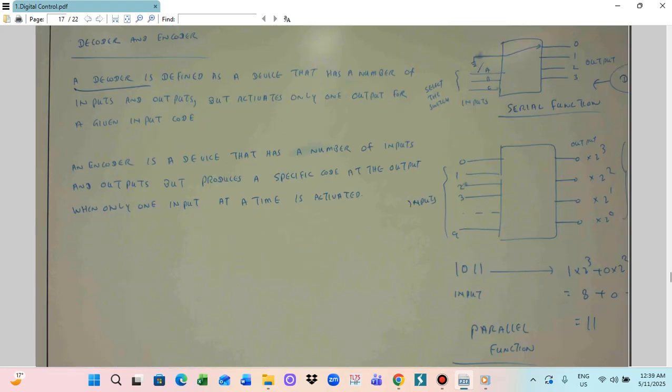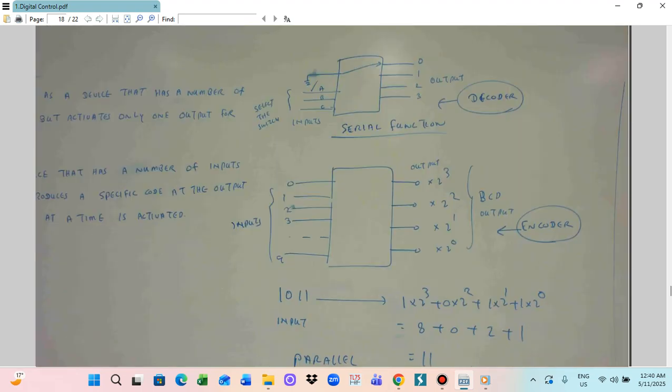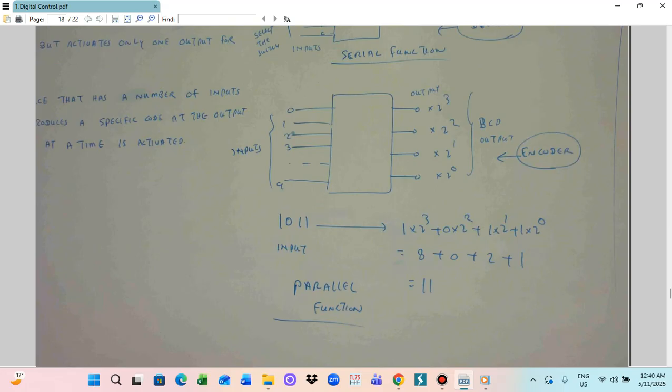So now this is for the decoder system. In the decoder system we use a wheel. The wheel has to be driven by the motor. So the input is a continuous signal. The continuous signal is produced by the transducer. Transducer means any speed is provided as a voltage by using the tachometer, and this voltage ignites the light. So the light glows based on the voltage. So this light beam may be the analog signal. This light is proportional to the speed. So this light signal is cut by this gray code field. So the output will be a digital signal coming out.